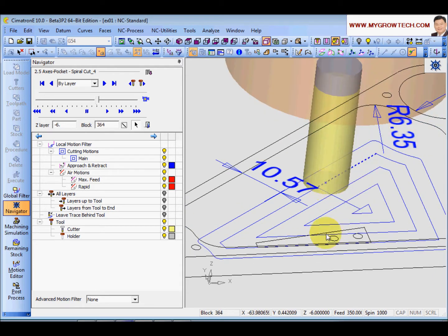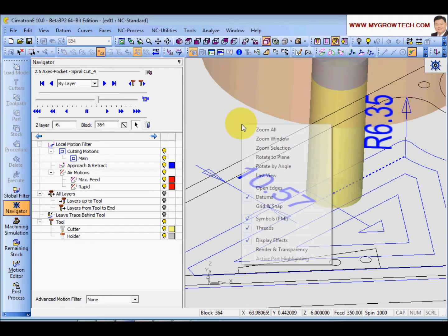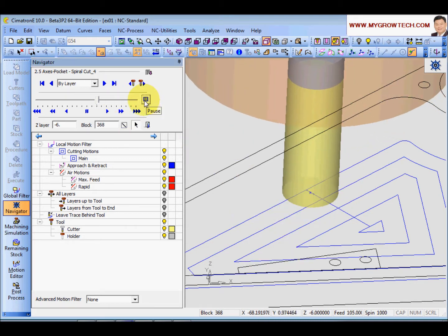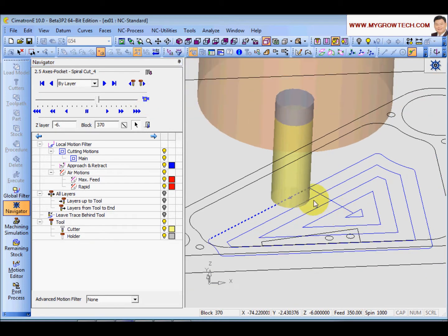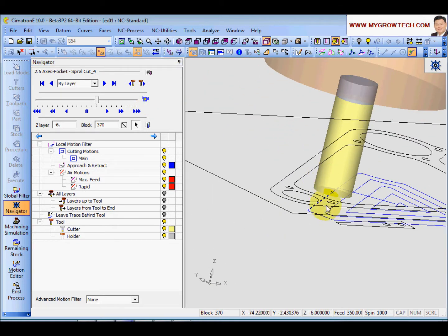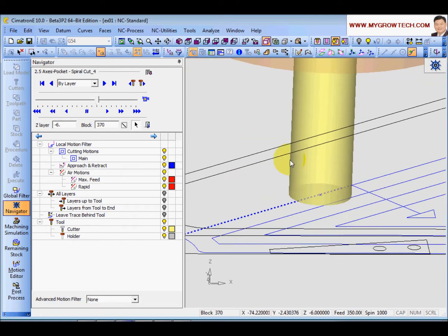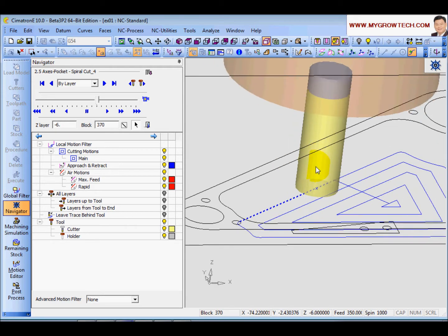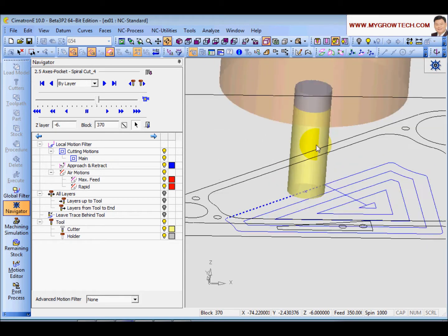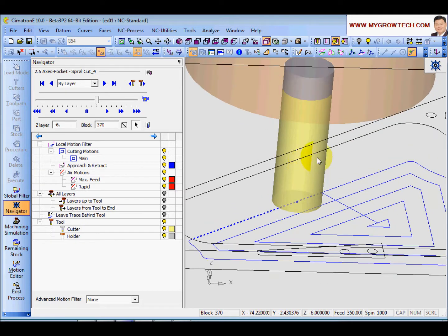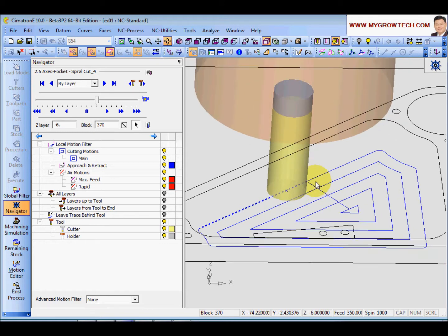Move the tool, come here, turn off the PMI and simulate. You can see also a normal approach. At the last area, the cutter contact to the wall is now almost 10 mm. So the contact is increasing, which also means the load is increasing. If your cutter is too long or not stable, you tend to vibrate and get marking here, and this is not a good result.